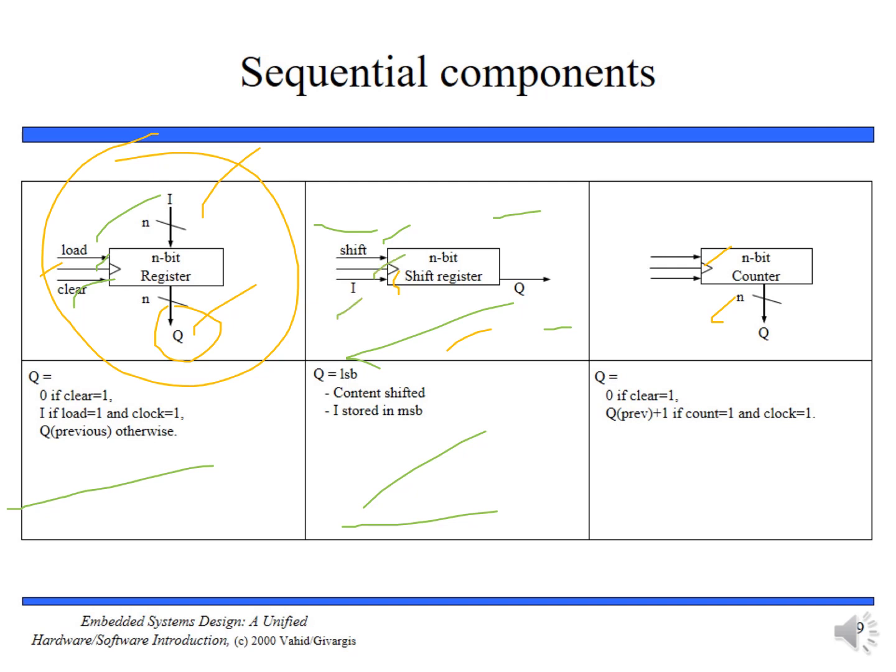What happens is that when the clock is rising and shift is 1, the nth bit is stored in n-1, meaning it is shifted by one. Another n-1 bit will be stored in n-2, so the bits keep shifting. This is a shift register. Because the bits cannot be stored in parallel, it is serial.